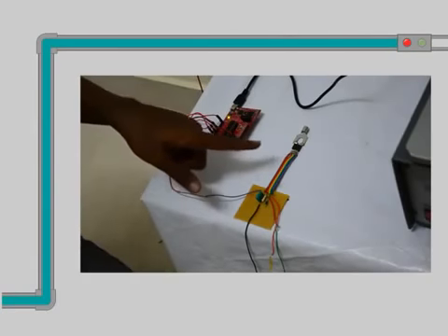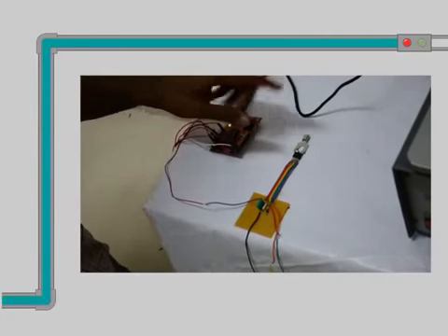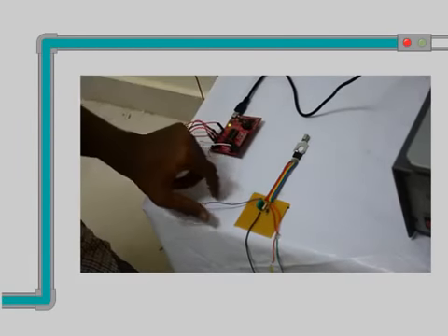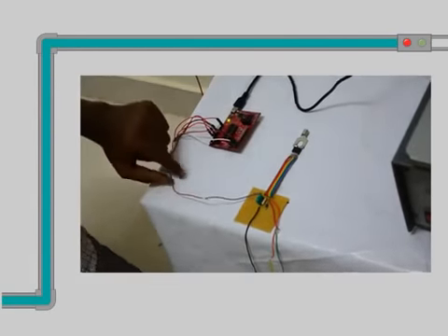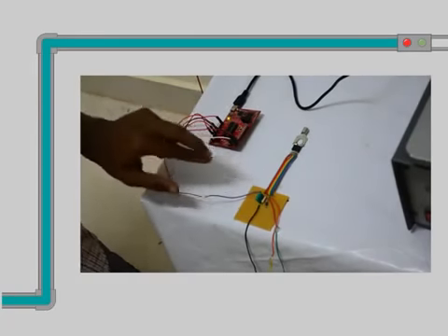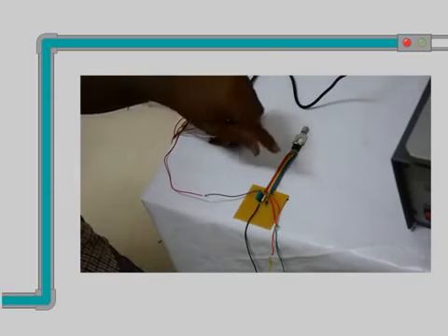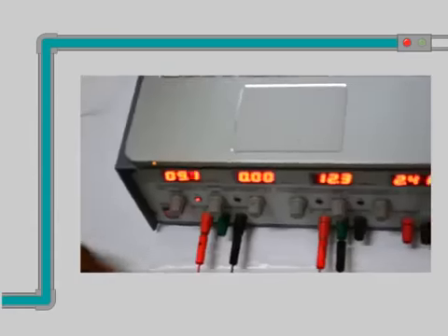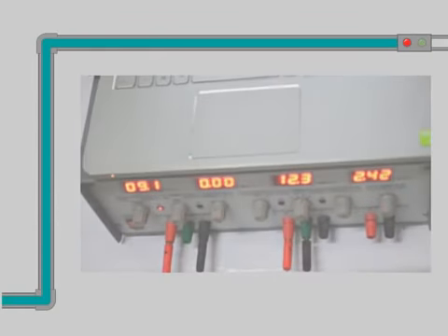This is the DRV101 circuit provided by Texas Instruments. Here we are using it for driving the solenoid valve. The input of this pin is given from the MSP430 through pin number 2.4. A potential difference of 9 volts is applied throughout this circuit. At last, a potential difference of 12 volts is given throughout the solenoid valve.